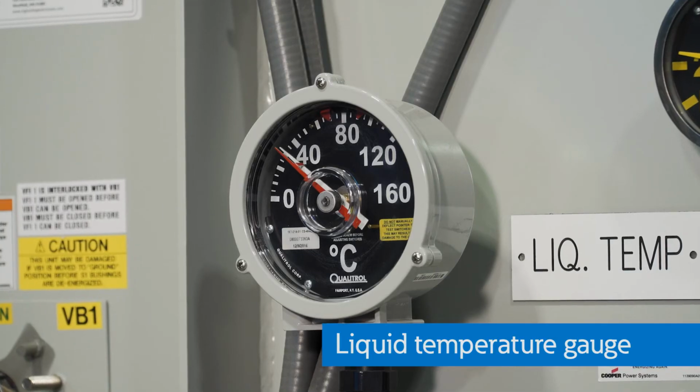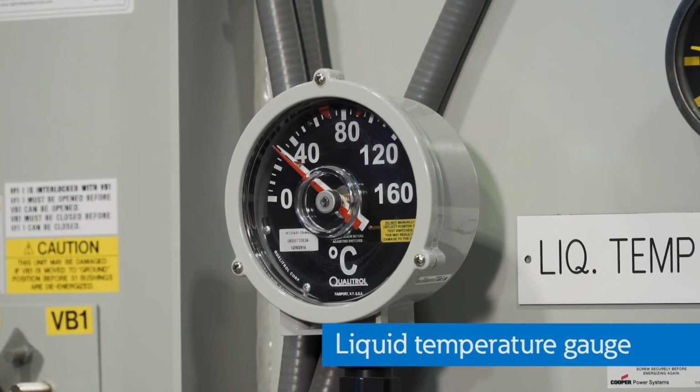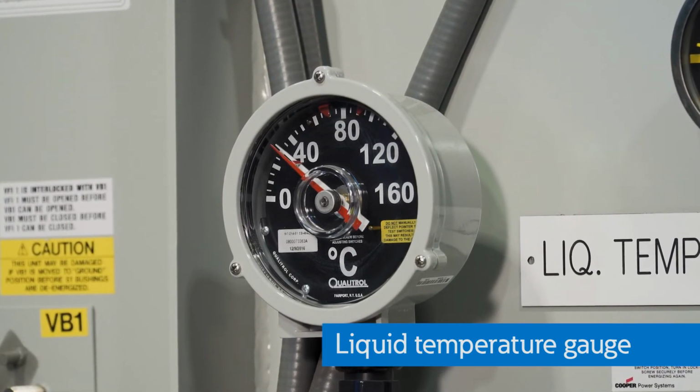The temperature gauge is furnished to indicate the top liquid temperature in the tank in degrees centigrade. The temperature-sensitive element is mounted in a leak-proof well, permitting removal of the thermometer without lowering the oil level. The device is furnished with an additional red pointer to show the highest temperature attained since the last reset. To reset the maximum indicator, turn the knob in the center of the dial.